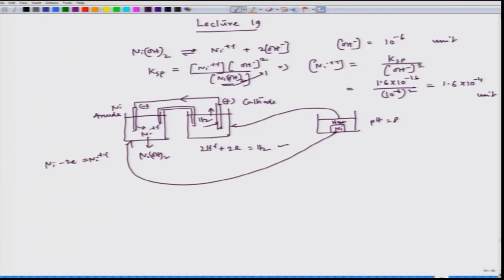Now, when we have this situation, because we are assuming that the nickel is corroding, this side should always be positive, this side should always be negative. So, the potential E1 which is set up on this right side should be greater than the potential on the left side. And of course our convention is we will take reduction potential.